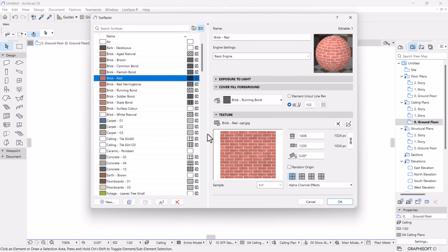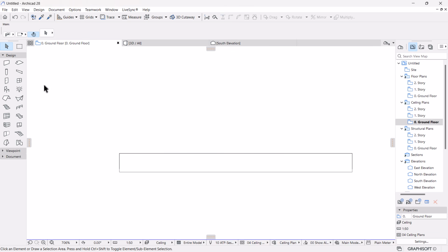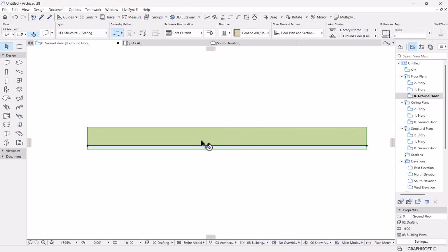So let's go here under floor plans, and currently this wall, I'm going to go to the top under the info box and access the structure of this wall. We have different types of structures, either basic or composite.